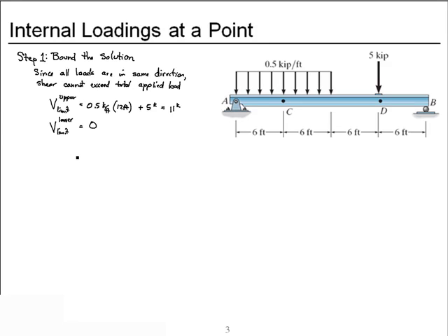Now for moment. Using the same process we're about to follow in this problem, you could derive that the peak moment in a uniformly loaded, simply supported beam is omega, the distributed load, times the length of the beam squared, divided by 8. I want to point out this is worth doing as an exercise and then memorizing, because omega L squared over 8 is a quantity or a formula that we'll use over and over again in structural analysis and structural design.